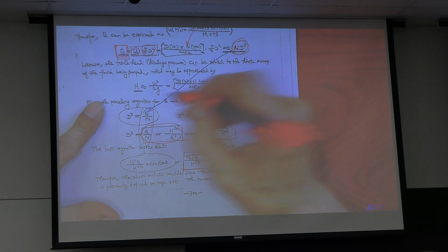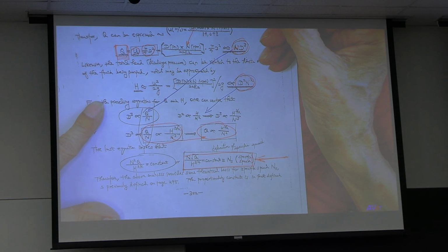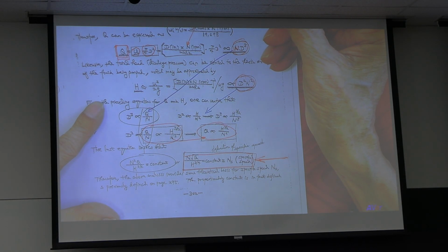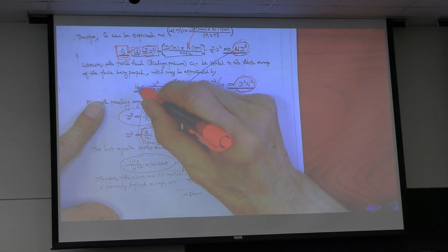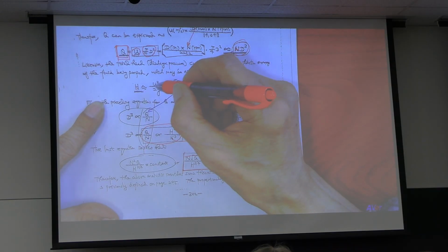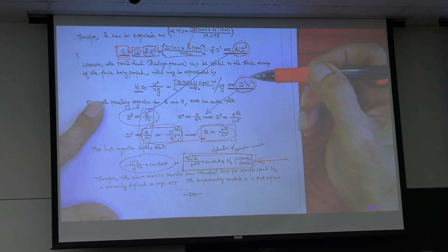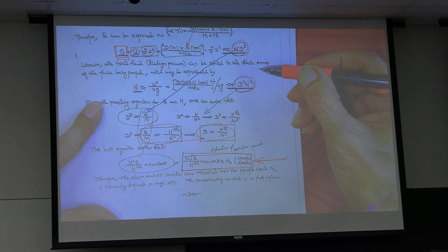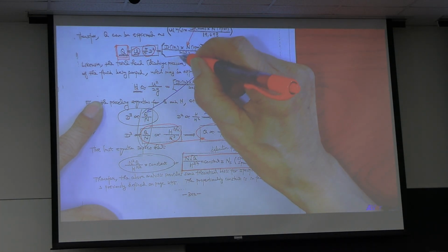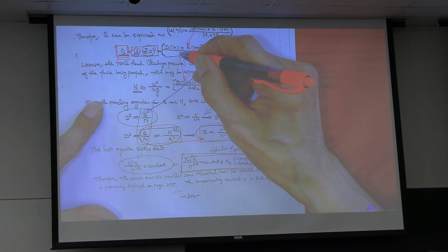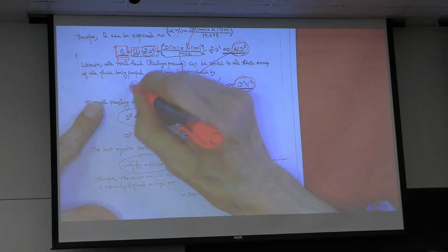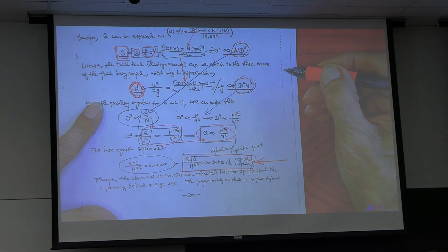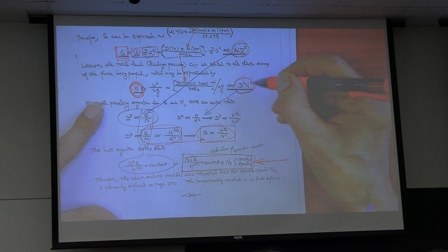Now, here, in the impeller, you mainly have pressure drop head, kinetic energy. Approximately equal, you plug in this relationship, head proportional to diameter square, N squared.